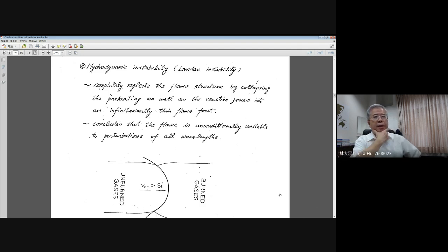We already studied premixed burning. Starting from the beginning, we looked at stable premixed flames, and we introduced the two most important burning characteristics that need to be identified to determine the burning intensity. One is the adiabatic flame temperature. The other one is the nominal flame speed.